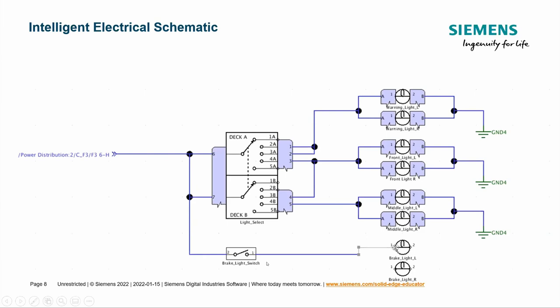When we put an element down on this schematic, it actually has parameters, meaning and characteristics. So the line being a wire would have a color, a gauge, a length. And the devices themselves could have a part number, a cost, a performance rating, and a website where you can learn more about the part from the data sheet. And notice we have all that information available to us without cluttering up the schematic. That's the key thing. All of these properties we can keep track of and capture are available when we need them, but hidden when we read the schematic.